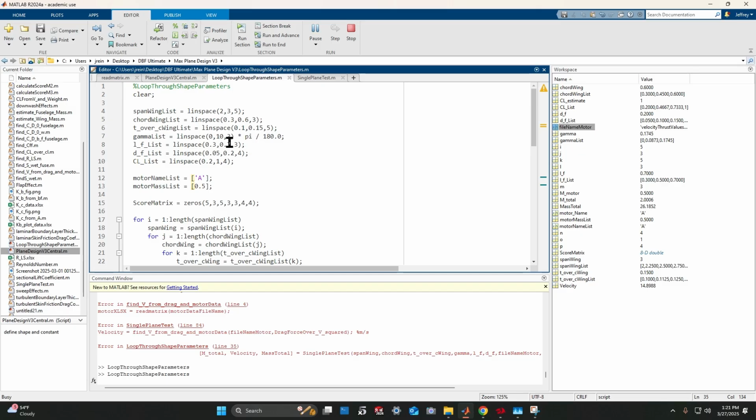Definitely the length and diameter of the fuselage. There might be reasons why these are fixed at single numbers, so you would change these to 1 and just put in, for these two numbers, the chosen length and diameter. Gamma can also definitely be reduced to just one value of 0, so that makes it run 3 times faster since there's only one loop of it to go through.